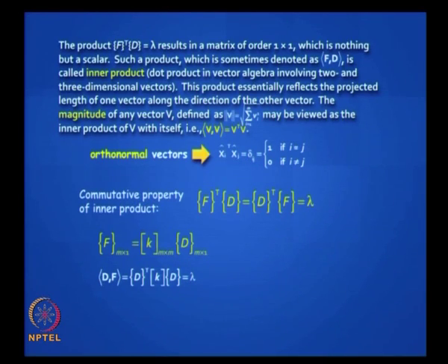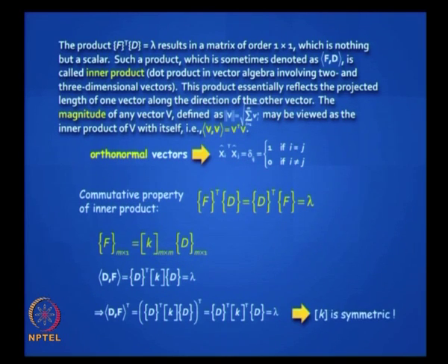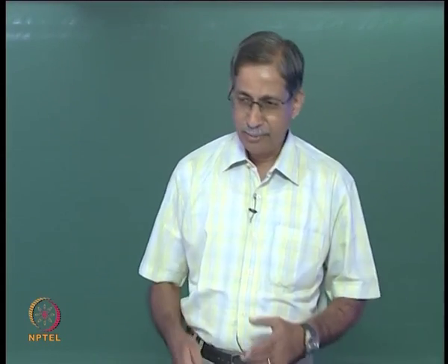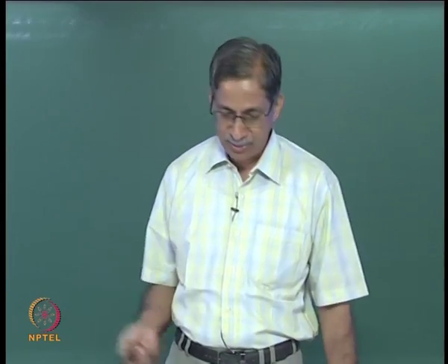So you take the inner product in this manner, you get lambda. Now you substitute, take the transpose of this, you still get lambda. Then when you compare these two expressions, d transpose kd is the same in both, but in one you have k transpose, so you end up proving k is equal to k transpose. So it is a very elegant mathematical proof of why the stiffness matrix must be symmetric. We will study symmetry from the structural analysis point of view later.